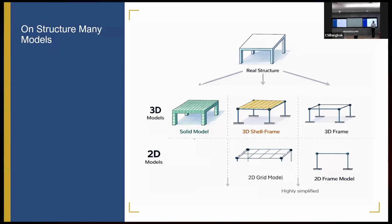But more importantly, it will give you results that building codes do not recognize, because there is no bending moment coming out of this one. There is no shear force coming out of this one. There is no torsion coming out of this one. All your design codes are written on bending moment, shear, and torsion. What will you do with the results? So that's the problem here.